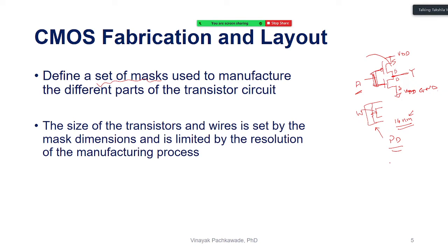When these dimensions are fixed, you use those masks or those rectangle layers for polysilicon, for N diffusion layers, for the metals, etc. So the widths and the lengths of each individual rectangle are already predefined. If you draw a rectangle like this, could be metal or polysilicon wire, and if you violate some dimensions, for example the width here and the width here, then when you run the DRC using the EDA tool, the tool will show you the error. It will immediately prompt the designer: go back to your design, reduce this width here. So you will have to adjust your mask again. Okay, so these are basically mask layers.